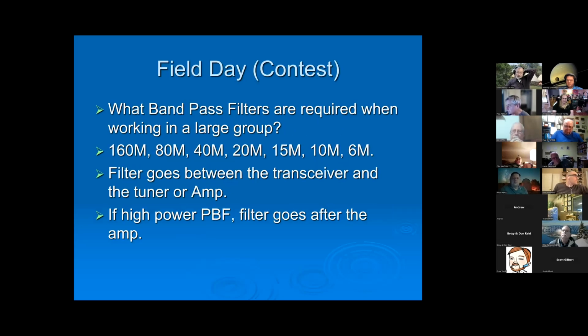Okay, field day. I think everybody's experienced it enough where we always have bandpass filters around. We pretty much drill it into everybody that you figure out what band you're going to operate on, and you check out a bandpass filter for operating on that band. And that keeps ugly transmitters from transmitting any kind of garbage out there that scrambles things for everybody.